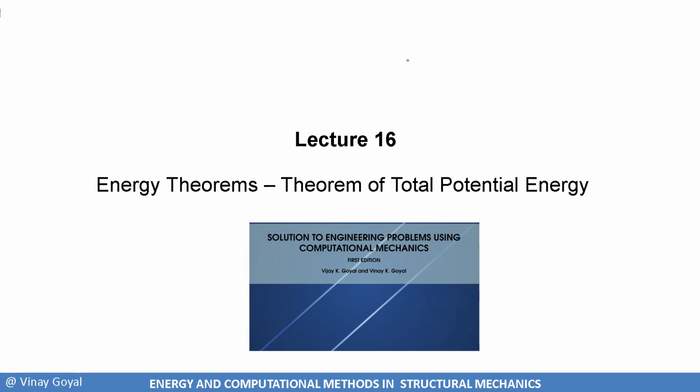In addition to that, we then developed the kinematics and described why we need to develop the idea of strains, because strains are normalized quantities that tell us how things are straining. Just by looking at a wing deforming 40 feet doesn't tell me a lot about where the structure is going to have a lot of strain. And so that's why we looked at the idea of strain. There are six components of strains, and we developed that. We demonstrated it was symmetric, and we also demonstrated it could be developed by using the idea of kinematics.